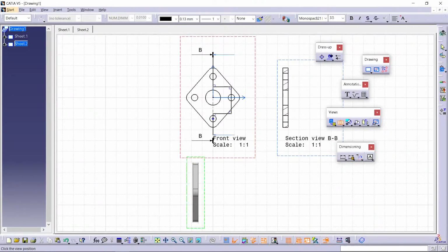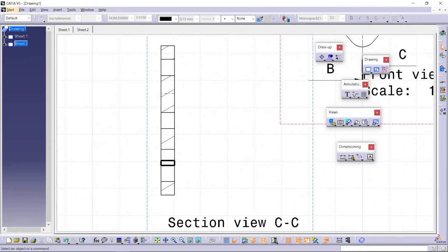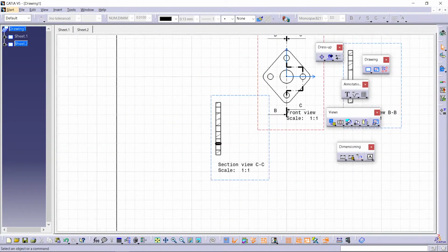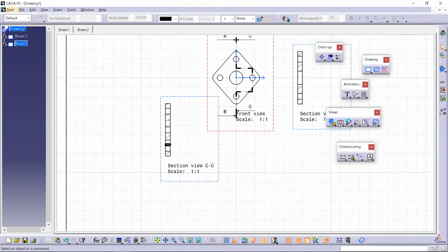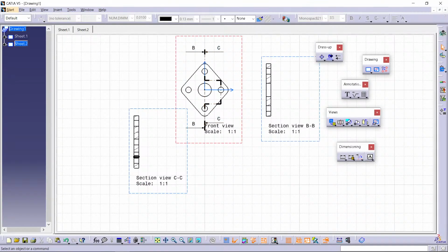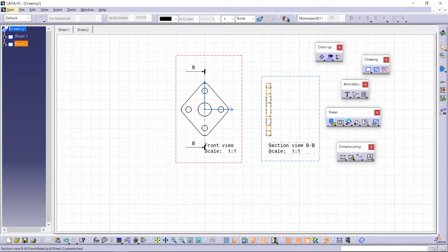Here you can see three holes are involved. This is your complex offset cut, and you can see there are also three holes involved, but in a single cut. Here three holes are involved, but I have given multiple cuts, meaning a complex cut. Now the next one is your align section view.